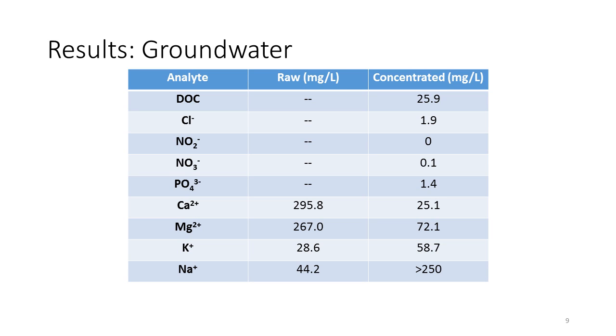And then the other thing I'll point out is one of the issues with this system moving forward, Mike, you probably know this, is sulfate. Yeah, and one of the reasons we did not want to freeze dry this is because, especially in the groundwater, the sulfate concentrations are really high. The reason we don't have numbers for them is that we have to go back and run ion chromatography in a different mode to be able to get it because it's so large in the concentrate. So I wanted to point out the issues with sulfate when you do that.